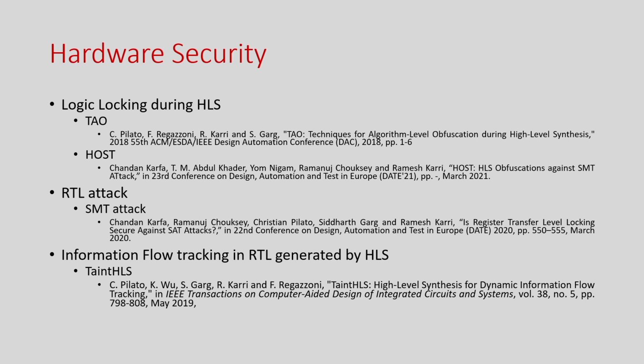We have already discussed in this course that because of fabless production of ICs, your IP, or intellectual property of the design house, goes to a third party, and there may be some rogue or untrusted employee there. They might steal the IP, they can do overproduction or they can do IP piracy. And to stop that, logic locking is a very popular and novel technique that evolved.